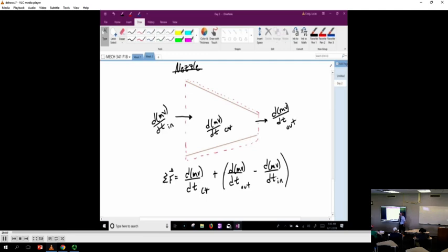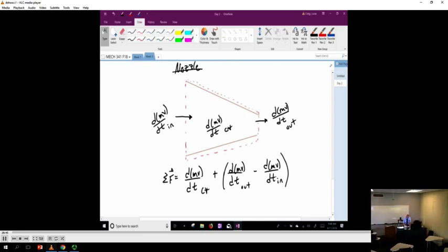Remember? What's dm/dt? The change in mass over change in time? What do we call it? m dot. So it's the mass flow rate times velocity coming in, which is a force. And then you have stuff going out, which is also another force. And then that is basically your mass m dot times velocity of the control volume. So you see how these are momentum, but they could be related to forces. So the way we write this, for your case, is this way.